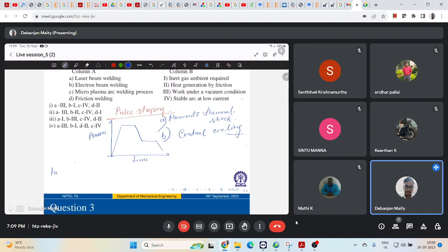Then also you can use high peak power initially to start melting. Whenever you have this molten material, the absorption rate increases, right? And then you reduce the power. That's why you basically shape your power distribution over time, depending on the different material combination.